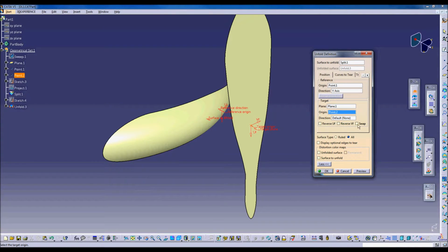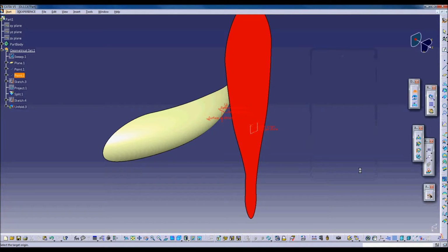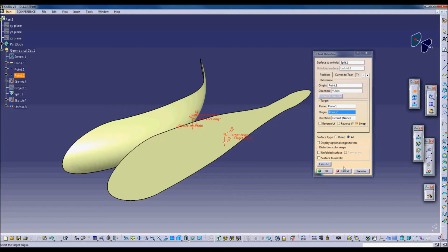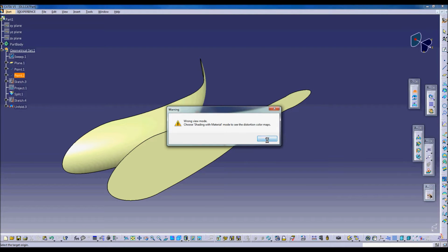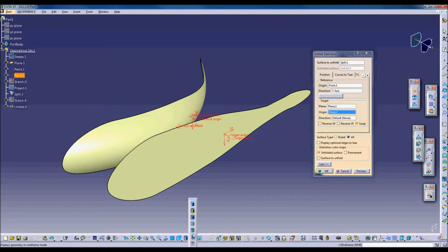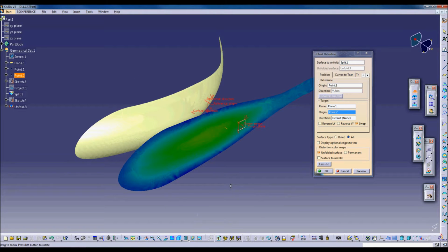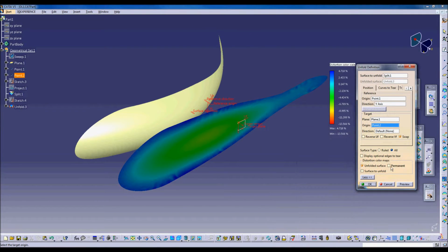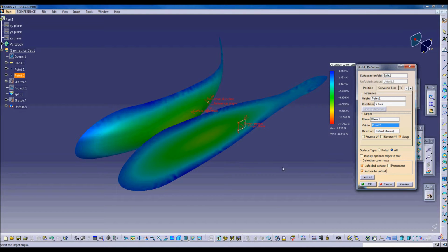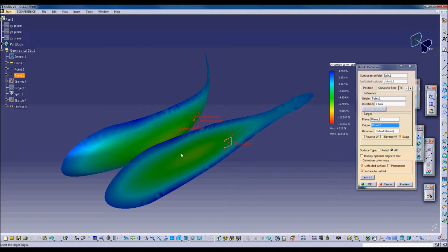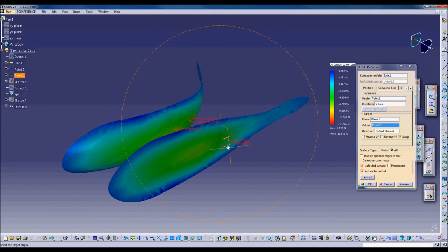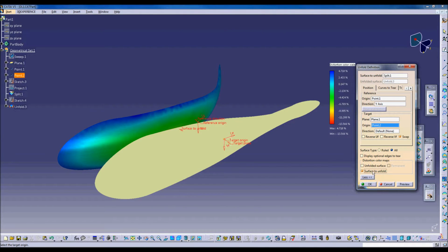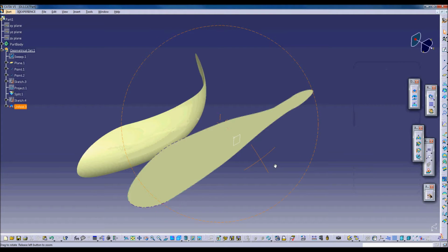And because it's going to have to deform it, well, I'm going to change the orientation first, but because it's going to have to deform it, there is an option for showing how much it is going to be deformed. So you can actually display the deformation amount. Change to the material view, and you can see that it's showing by percentage the amount of deformation to actually achieve the flattening of this doubly curved surface.